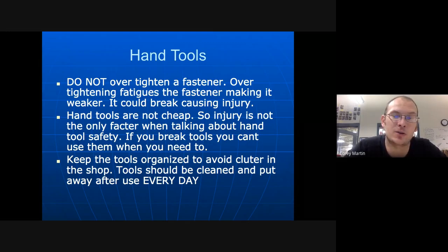So let's say that you do a tire rotation on somebody's car, or you do a brake job on somebody's car, and you hammer on all four wheels with an impact wrench. They get 10 miles down the road and run over a nail. That has nothing to do with the work that you performed. However, they are now going to have to change their tire and put a spare on. They probably are not going to be able to break those lug nuts loose with the basic tire tool that's provided with the vehicle. So we will use a torque wrench.